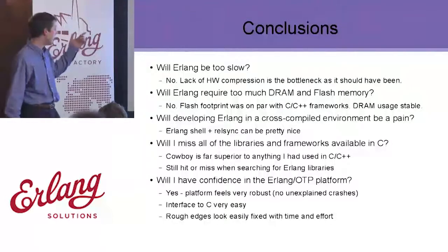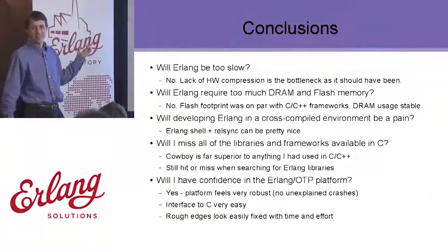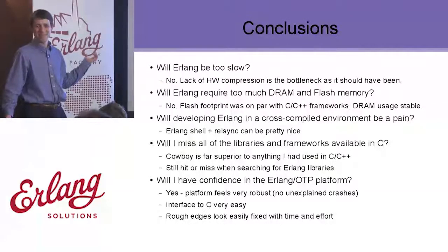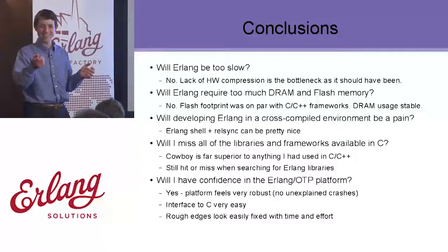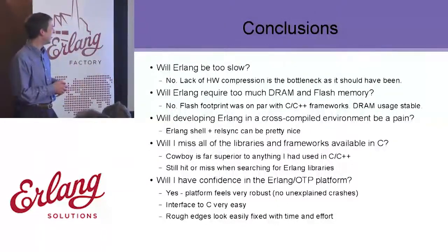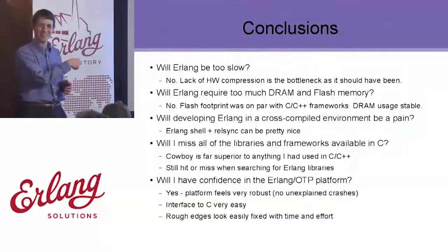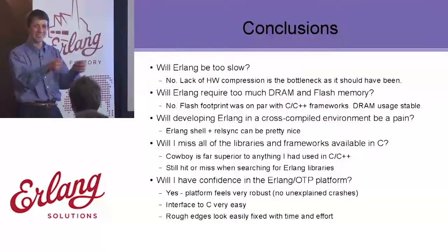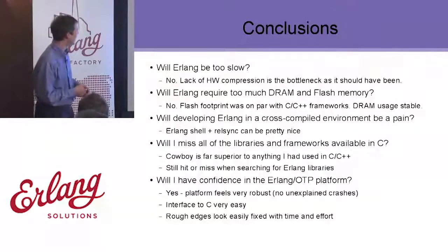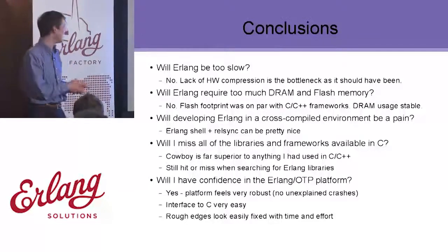DRAM and flash, we just saw that. Cross-compiling actually turned out to be nicer. Once I got Rsync working, it became a lot more enjoyable. Unplugging and plugging the SD cards got old, even though I could program them in a couple of seconds. And also, if you do that too much, you'll break the SD card programmer because you'll wear out the slot.